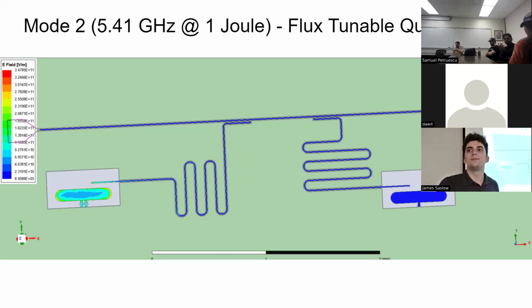But when you're trying to drive the signal, now you're driving a chain, from your launch pad to the CPW to the coupler and then to the resonator. Now that's like a whole big network. Exactly. And so once you have a complicated system like that, you can't really talk about individual parts. That's why it's important to simulate it as a whole, because the eigenmode frequencies could shift if you add something new. So some different behavior could happen.